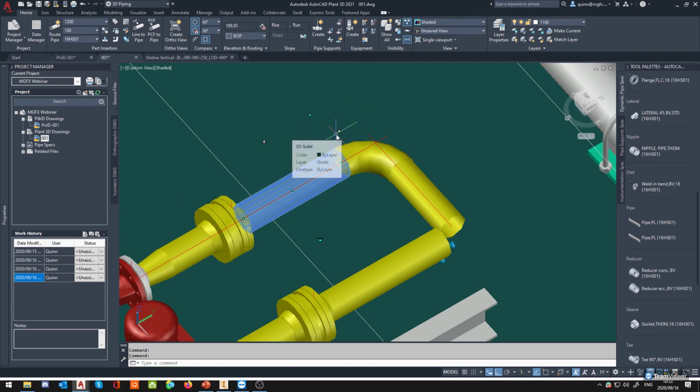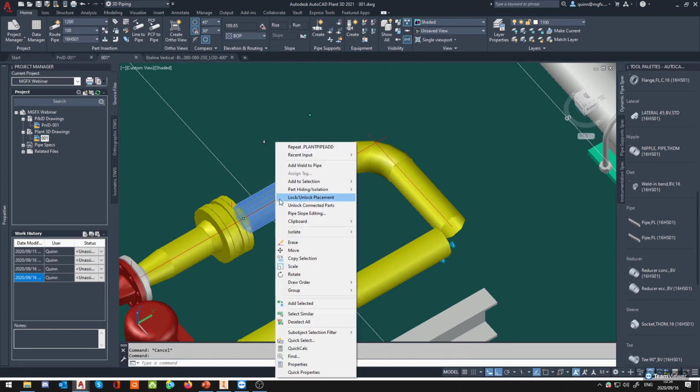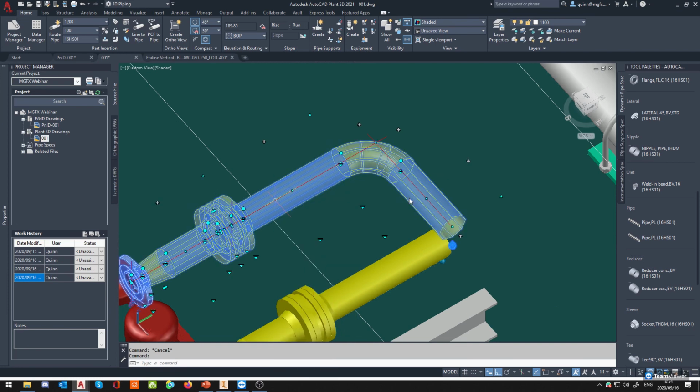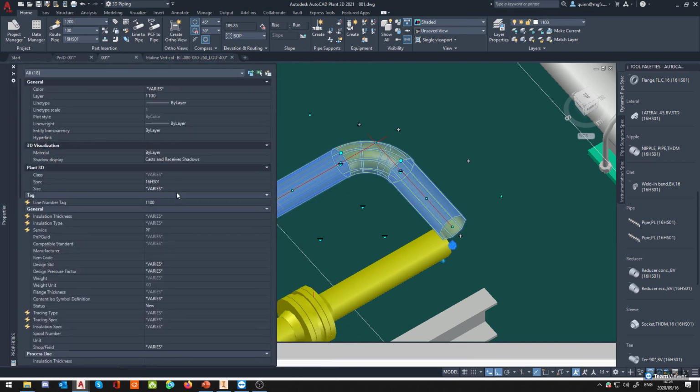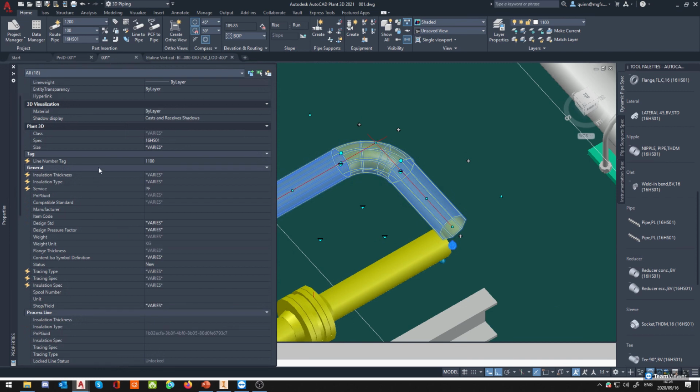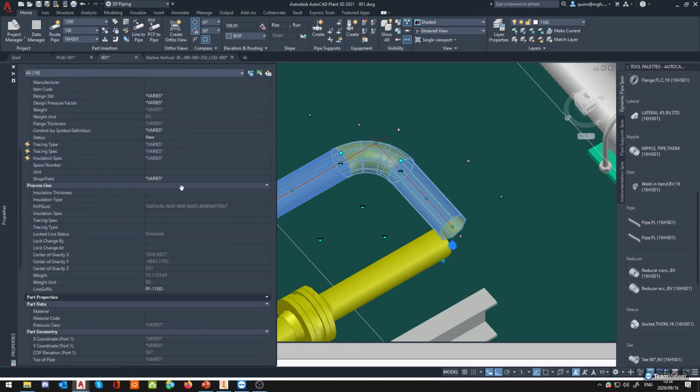When you had insulation on one of your previous systems, it used to just upsize the pipe. When you're upsizing the pipe, it can be a bit weird visually. So what they did with the newer release is they allowed us to select the pipe or pipe number, go down into our properties, insulation thickness. Maybe I'm changing this. So this can be edited in the backend.